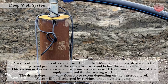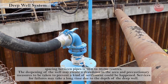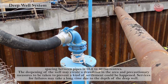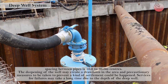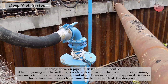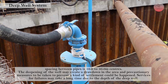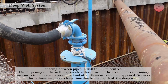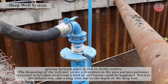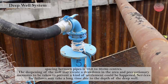Water will be discharged by turbines or submersible pumps. Spacing between pipes is 10 meter to 30 meter centers. The deepening of the well may create a drawdown in the area and precautionary measures are to be taken to prevent settlement that could happen. Servicing for failure may take a long time due to the depth of the deep well.